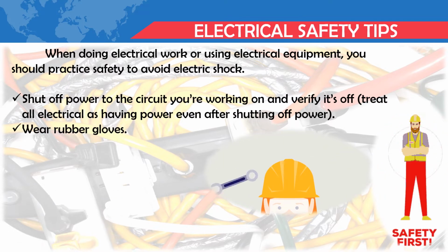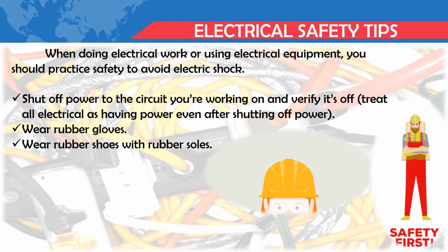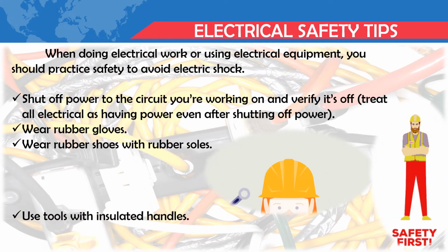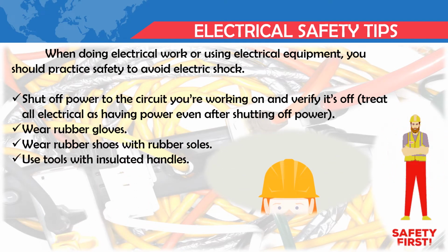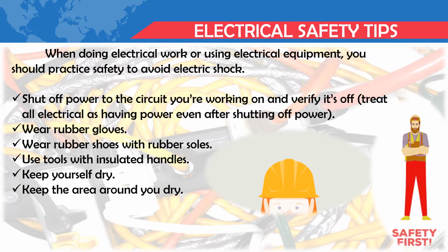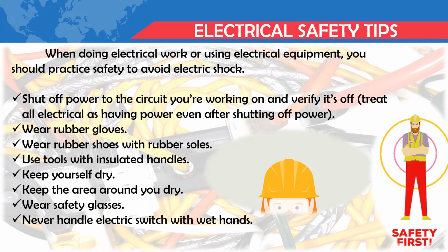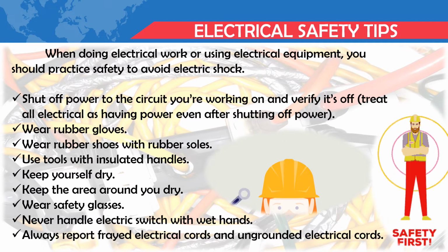Next, wear rubber gloves and rubber shoes with rubber soles. Use tools with insulated handles. Keep yourself dry. Keep the area around you dry. Wear safety glasses. And never handle electric switches with wet hands. And the last one, always report frayed electrical cords and ungrounded electrical cords.